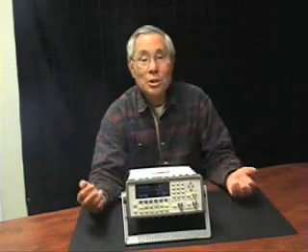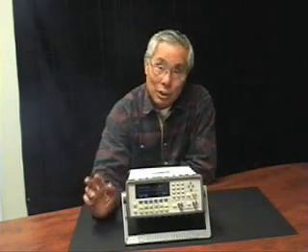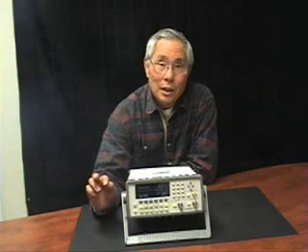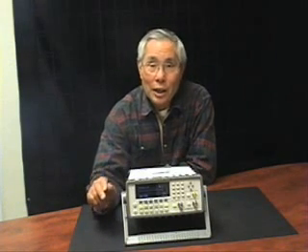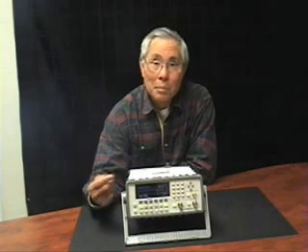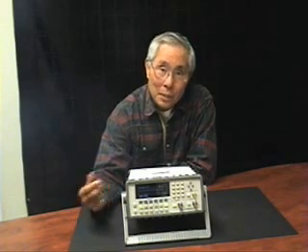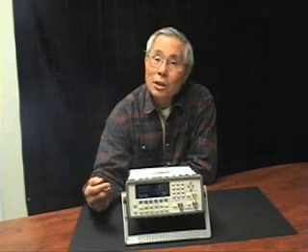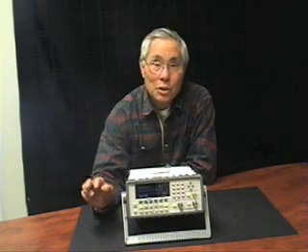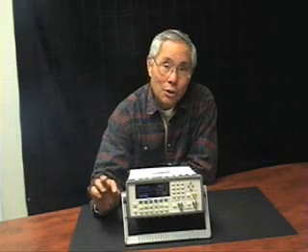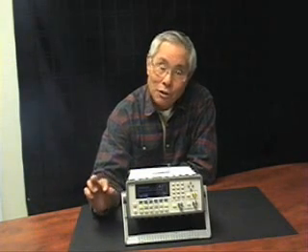So let's say you're a crystal manufacturer and you're measuring frequency, and you want to know statistics of the crystal that you're looking at. You can look at things like mean. You can look at min-max, the ratio of min-max. You can look at delta, and you can look at standard deviation. So if you have particular acceptance levels within which your oscillator has to fall, this is a good way to do that.